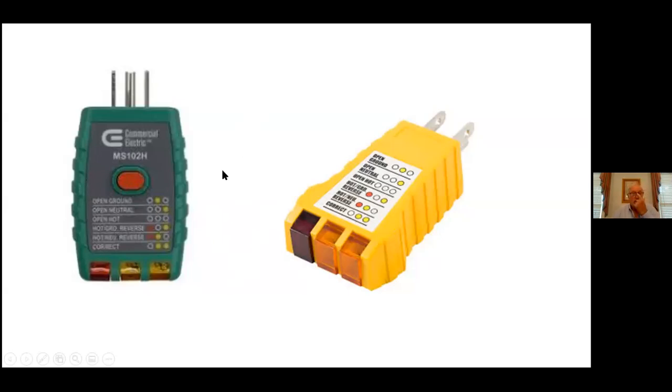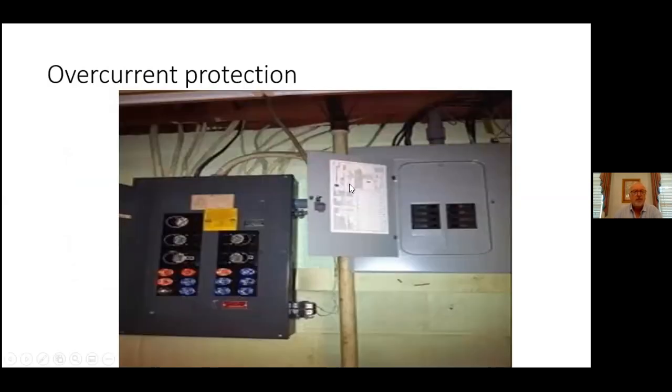correctly. So when we would test with these testers, and then perhaps it wouldn't reset, we would know that that particular outlet was not really grounded. It was just a GFCI that was placed there, and therefore it would have to be repaired. So you would look for that in your report under the electrical system recommendations, that it actually is repaired by a qualified electrician.